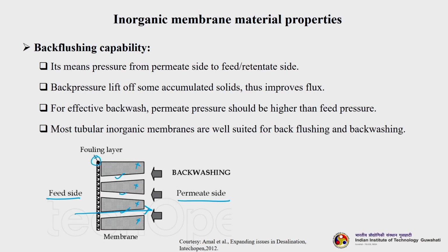So, this back pressure lifts up some of the accumulated solids, thus improving the flux. Many times, as I told, the solids are getting deposited on the pores of the membrane as well as here. So, when you are doing back flushing, usually water is used at a certain pressure. Under this pressurized condition, water will wash away these solids which are deposited inside the pores as well as on the surface of the membrane.